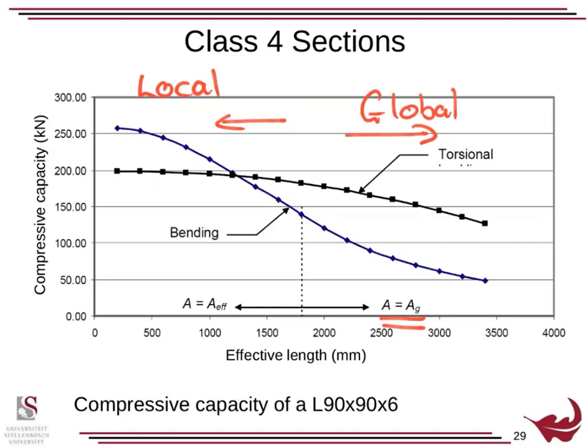That's also the effective length does influence whether local or global buckling occurs. So global, once again, the entire section would buckle between supports, like that, whereas local buckling, my angle would just experience a little buckle along its length. I've drawn that really badly, but I would have a local buckle, for instance, on my angle there. Part of the section would fail.